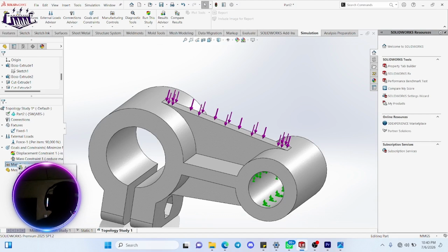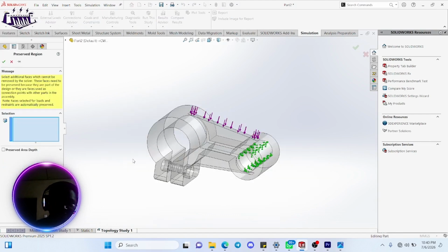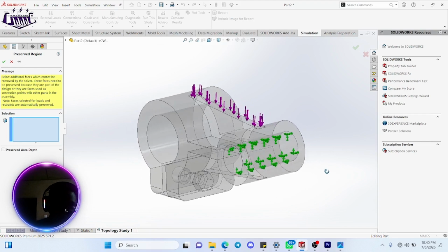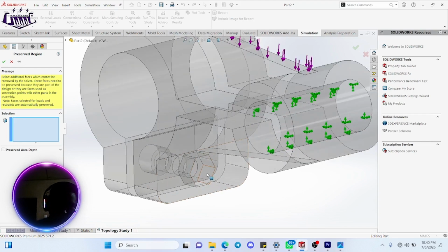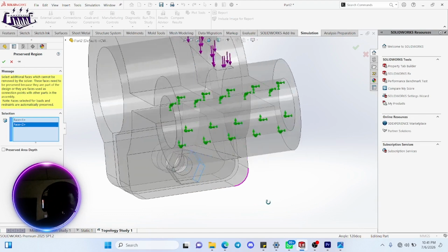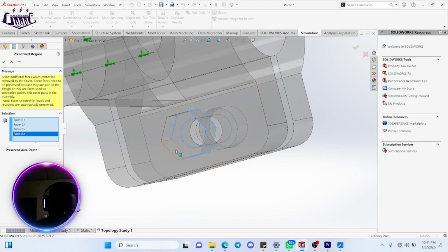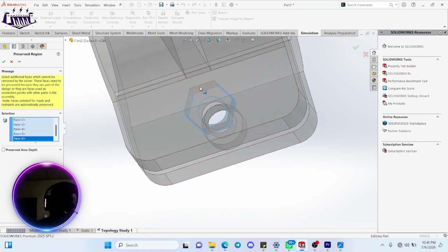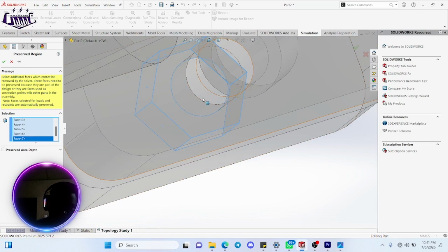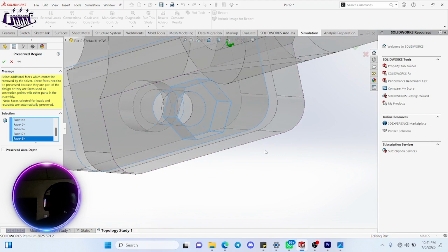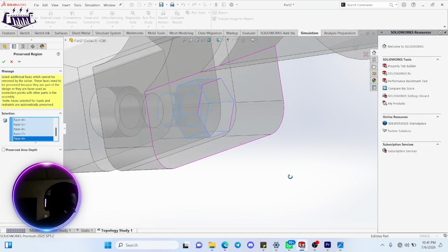Next thing we need to do is the manufacturing constraint. If you just go ahead, it will topologically optimize everywhere. But most times it's very important that you tell it where to preserve. You understand? So for me, where the bolts are is very important, so you should reserve all these parts. So I'm going to select those parts, because you should not optimize and leave this part out. It's very important that it preserves this part.